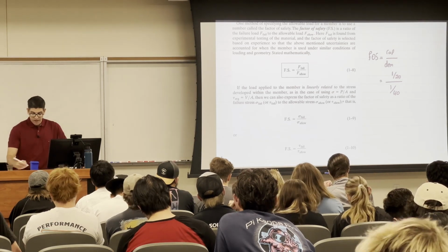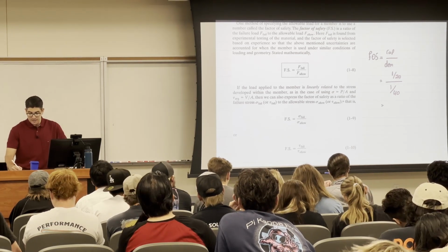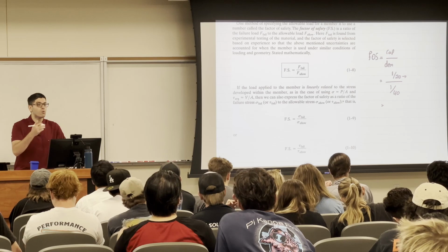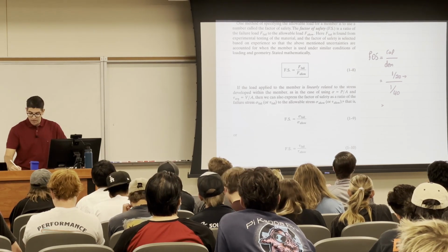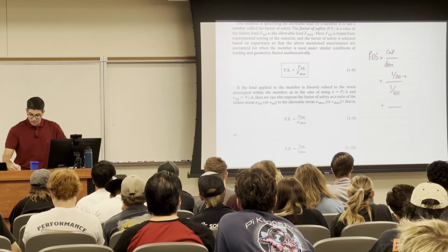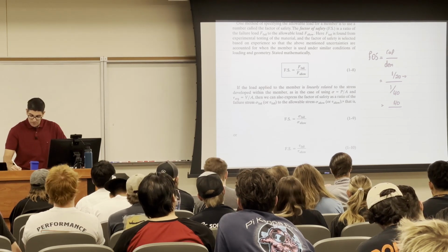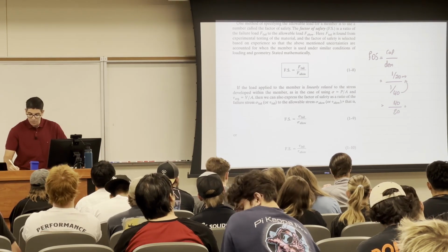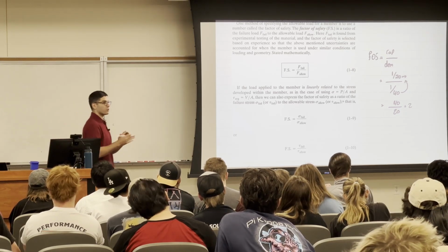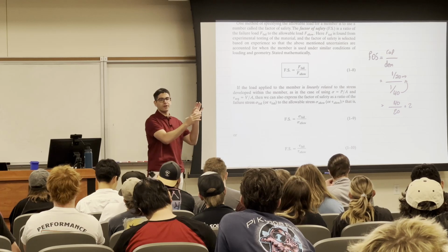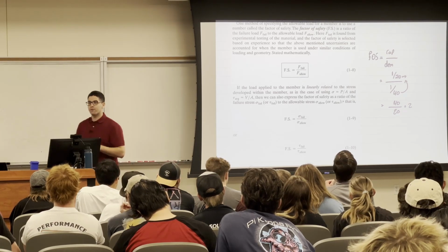So now, this is the capacity, 20, below which it is going to break. So I want to increase the area. If I want to put it in the right way, I'll put 40 up and 20 down, so that I end up with a factor of safety of 2. Okay? So now if you want to apply a factor of safety, you can't directly put it in that equation. You need to do this kind of maneuver.